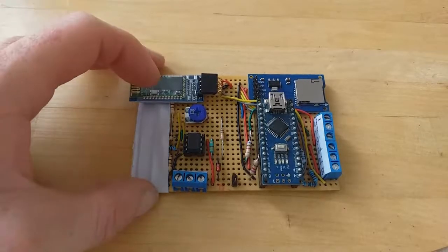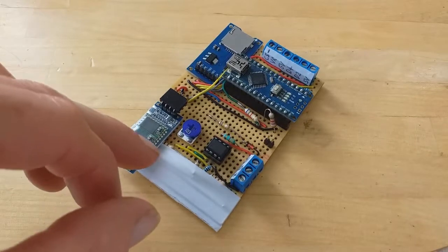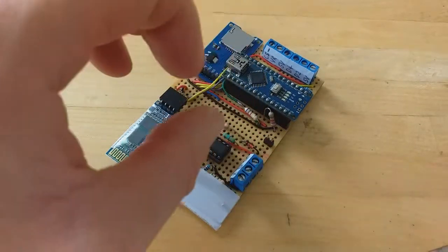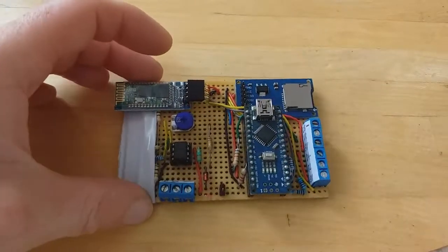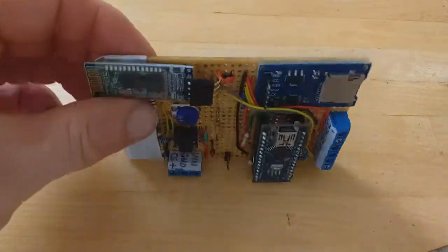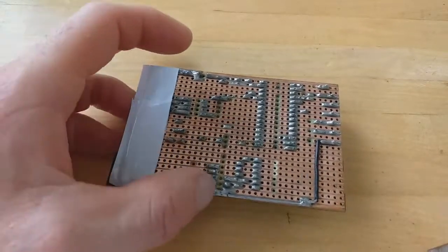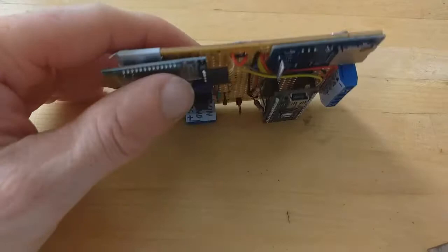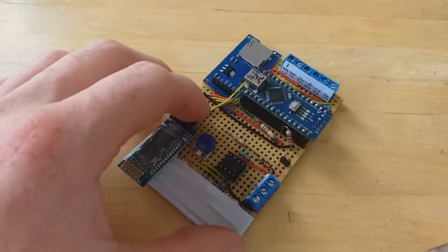I made a few little changes to the layout and wiring, and moved the connector block from this side over to there, so I only have wires on two sides now, which makes it a little bit easier when it's in a small box. So the current shunt runs around the edge of the board there. The current shunt's under the tape, and it runs around the edge there, which is okay because I'm only measuring up to 800 milliamps, so it's fairly low current.